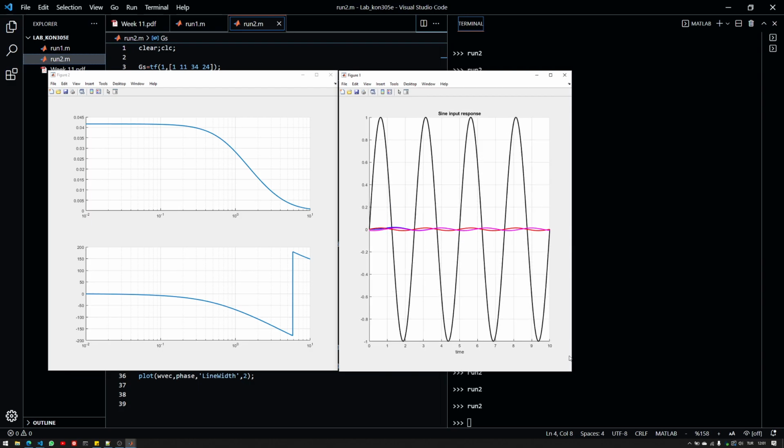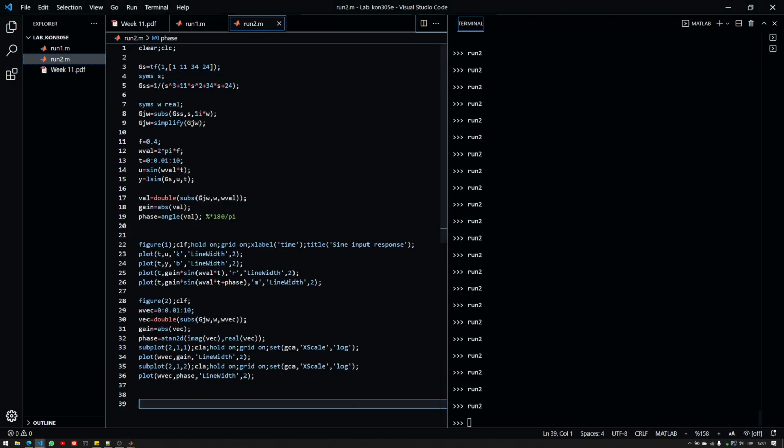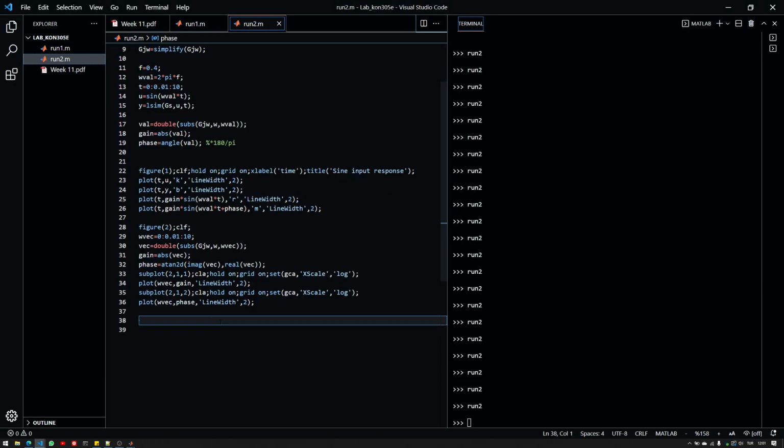Now, in order to determine the stability, I need to think of my controller and my system in the frequency domain. Let's type in the closed loop. What you can do is use K times G(s) divided by 1 plus K times G(s) and then substitute s equals j omega. Or if you have already done that, you can just use K and your G(j omega).